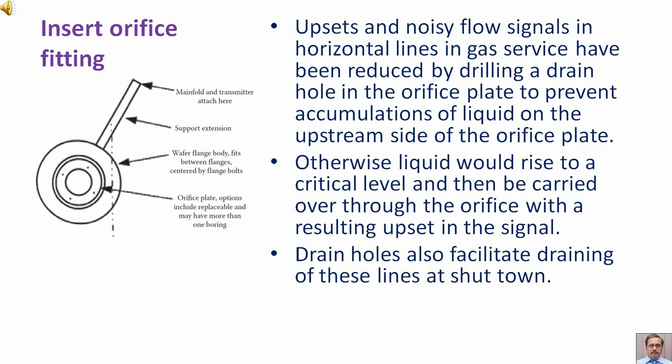Otherwise, liquid would rise to a critical level and then be carried over through the orifice with a resulting upset in the signal. Drain holes also facilitate draining of these lines at shutdown.